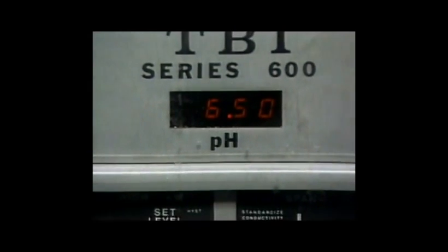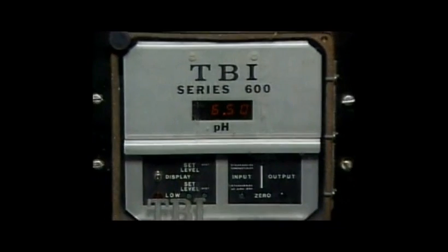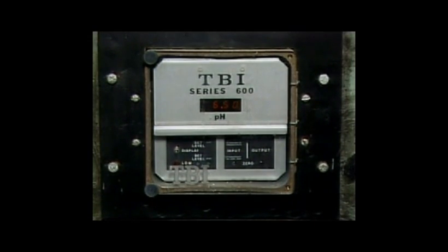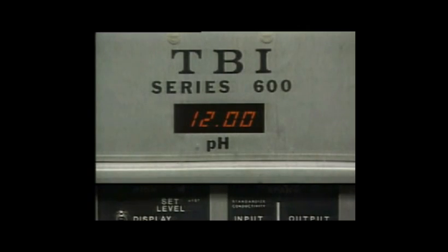A relatively low pH tends to increase the likelihood of corrosion, while a relatively high pH tends to increase the likelihood of scale formation. Acids such as sulfuric acid, which have a low pH, can be added to lower the water's pH when it is high. On the other hand, if the pH is too low, an alkali is added to raise the water's pH.